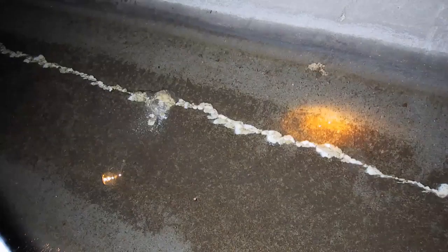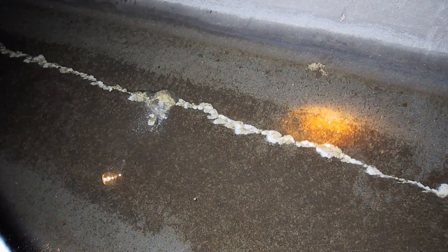So this is a picture of a pipe where you're actually seeing the autogenous healing happen. You may have seen this and noticed this in other things, like in a sidewalk after it's been raining for a while, or if you watered your lawn, you may see a crack in the sidewalk or a curb and gutter or any concrete, really the base in your foundation. A hairline crack, you may see this white efflorescent material. And this is actually the calcium carbonate, which crystallizes and seals in that crack.